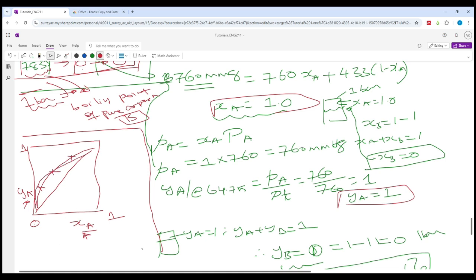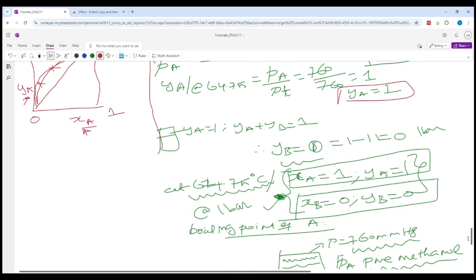and then try to connect these points. Another thing that you have to do as part of this problem is to plot the so-called TXY diagram, which is temperature versus x comma y. Maybe I can plot. Okay, temperature is on the y-axis, and let's express x in blue and y in green. If you plot temperature versus x, you will get something like this.